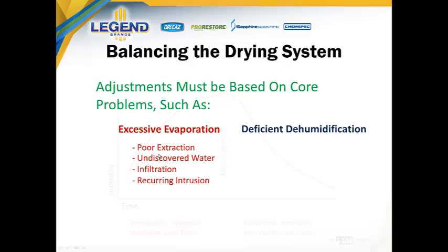And this is only halfway through the conversation. Let's go to the other side here. If in adding dehumidifiers you did your math wrong, then sure, we need to increase dehumidification. So recheck your math. Again, calculate for the cubic meters of air in the space. Reevaluate your scope. Is it really a small or a medium, or should it be a large based on what you're seeing? Once you reevaluate the math, if it's off, then let's add some dehumidification.